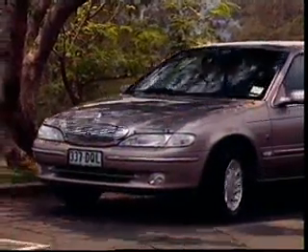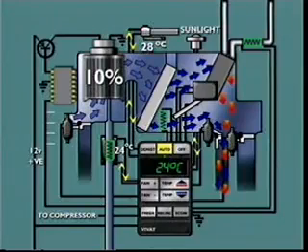As the vehicle is driven out of the shadow, the sun load sensor again changes its output, and this is registered by the electronic control unit. More sunlight means more heat radiated to the cabin interior through the cabin glass, so the amount of air flowing through the heater core may be reduced.